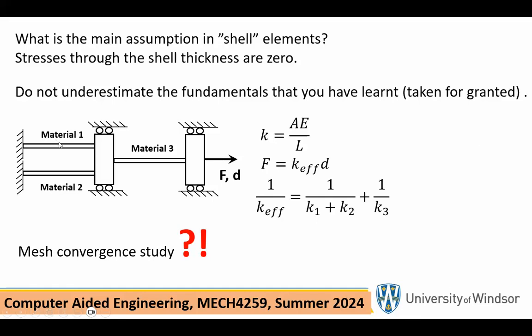So when you take the equivalent stiffness of these two, you add up the stiffness of material 1 to material 2, or bar 1 to bar 2. So it's going to be A1 E1 over L1 for that, and K2 is going to be A2 E2 over L2. Of course, they have the same L's, we know that. And then you add them, you get K1 plus K2. So these two springs acting in parallel can be replaced with a single spring of stiffness K1 plus K2.